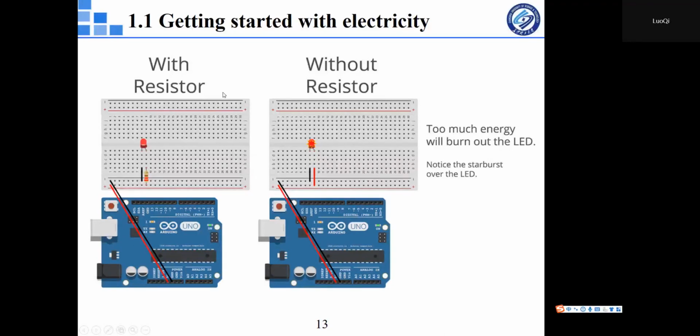You use a resistor in series with the LED to keep it from receiving too much current. The value of a resistor, or its resistance, is indicated by the colored bands on its body. Resistor color codes are covered in the next section.